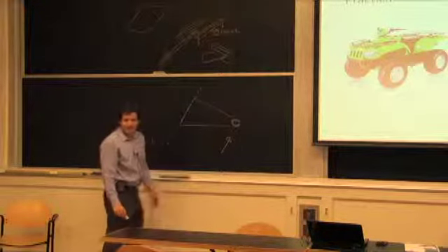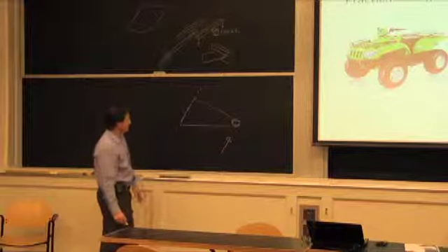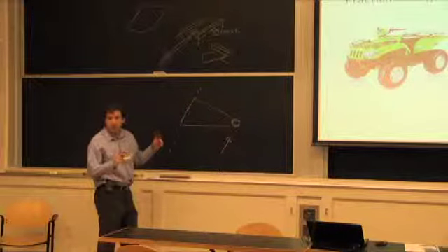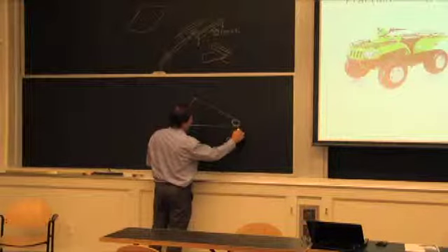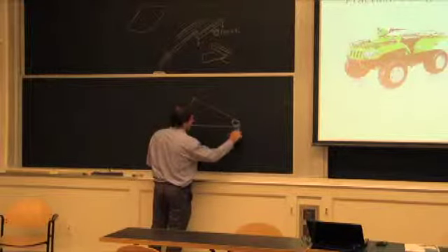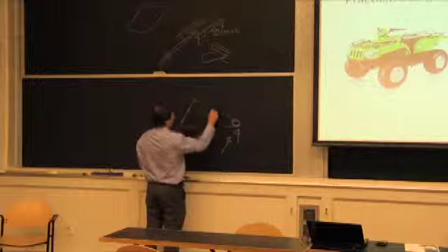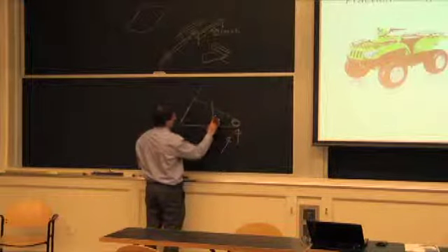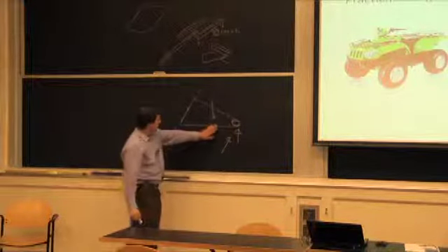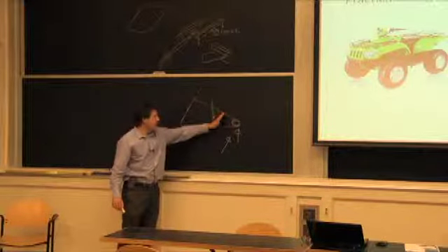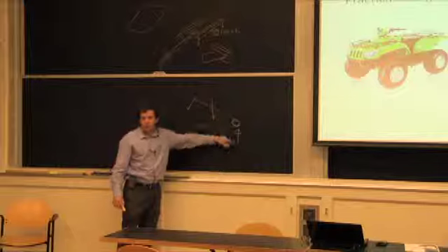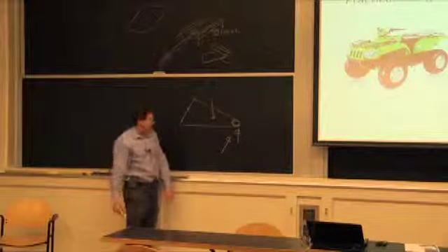So it's more or less of a joist or a truss structure. For a force coming from the ground, say this way, and that's resisted by the suspension we're going to put right here, this is the 2 tubes individually working in bending to resist the ground force.